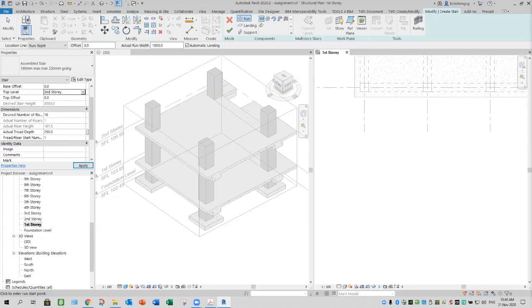But for terrace house design, more on residential, the minimum they can go is as low as 220. The tread, not the riser. Riser is fixed. You cannot exceed 175. It can be lower, but not higher.